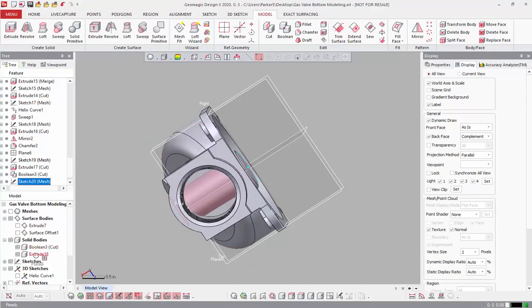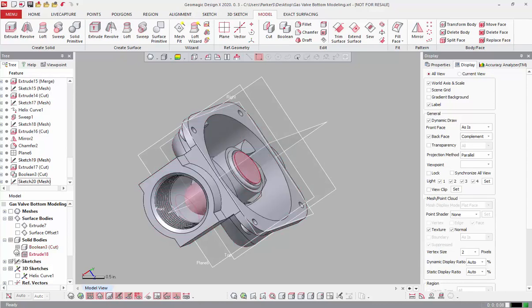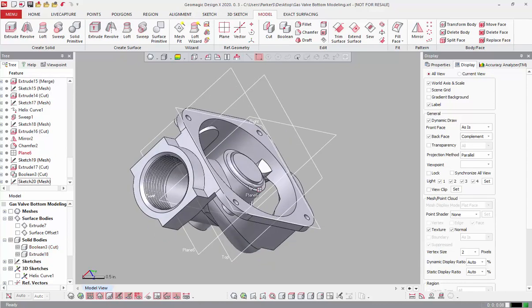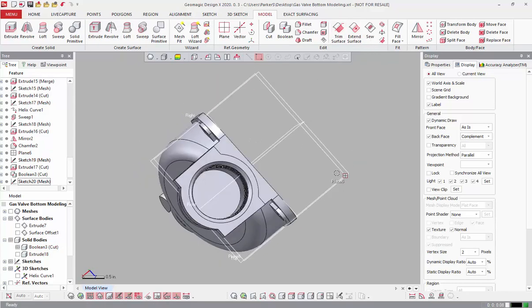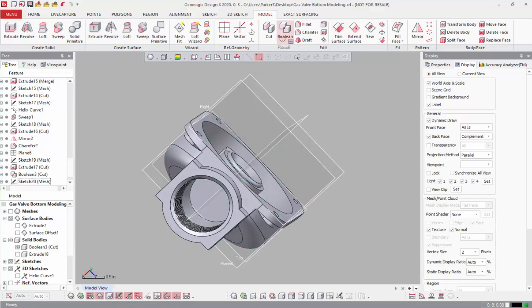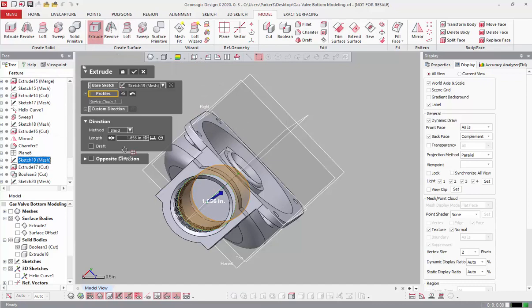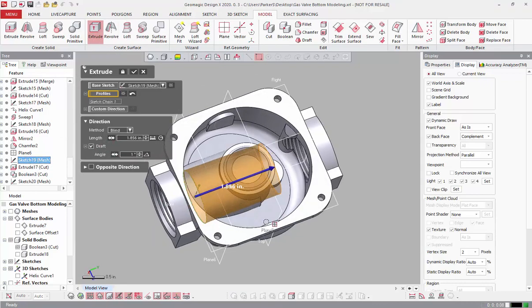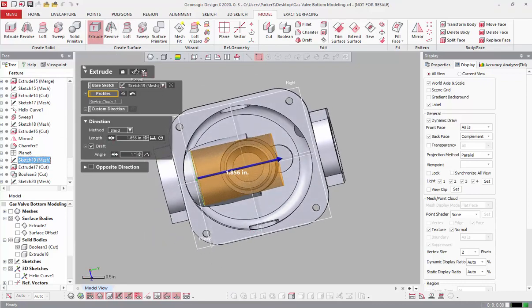Again, now I've got another solid body here. So if I can't make it extrude to where I want it to go, that's fine. What we can do is just say I want to do a, actually I can even take that same sketch that I did before. This might be an easier way of doing things. And instead of doing a solid extrude, I'll just do a surface extrude this time. Same taper. Make sure it passes all the way through that feature that I'm trying to intersect with it.